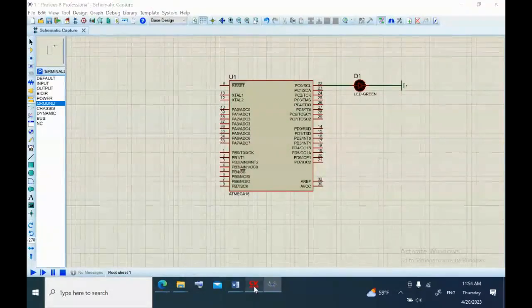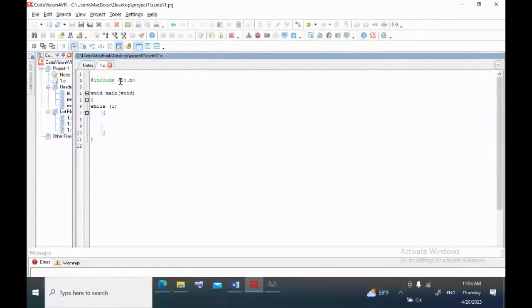But you see here in our coding, ATmega16.h is not added to my code. Actually, io.h is a general header file including all AVR families, ATtiny, ATmega, ATXmega, and all the types of each family, and it includes ATmega16 inside itself.